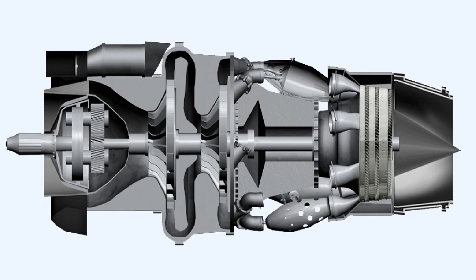In practice, it's not been found feasible to use more than 2 centrifugal compressor stages together. Excessive impeller tip speeds and extreme centrifugal loading prohibit efficient operation of a third stage. As a result of this, engine compression ratios of much greater than 12:1 are not considered possible using centrifugal compressors.